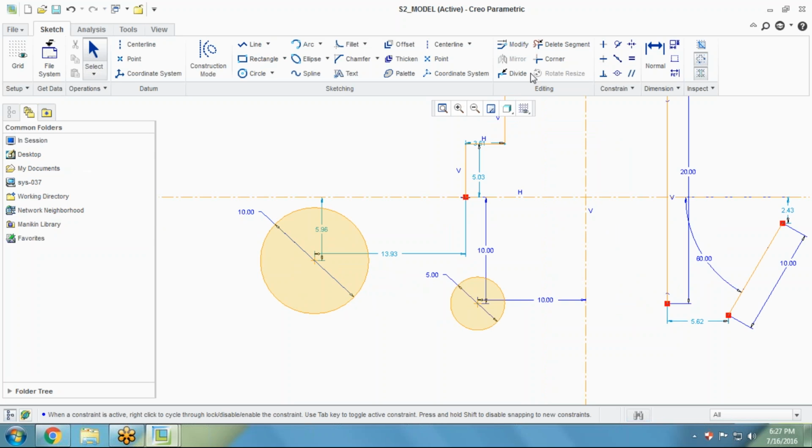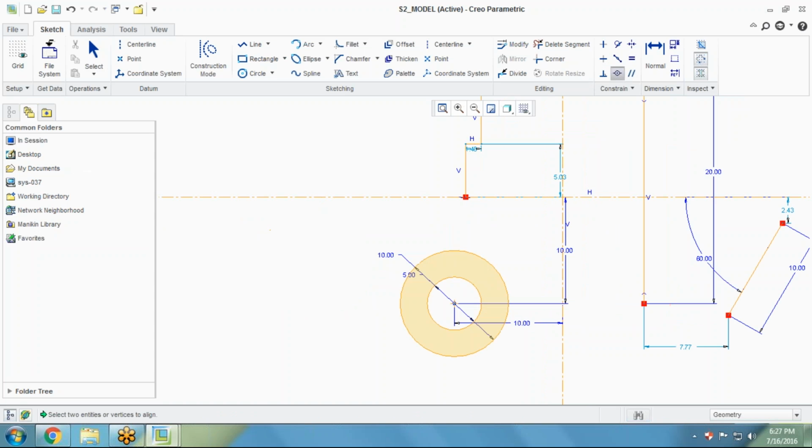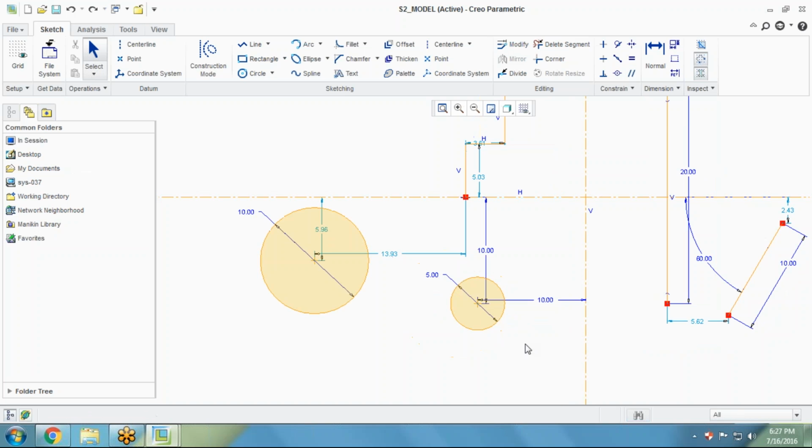So now the next operation I'm showing you is coincident. Just click on this point, click on this point. Now I'm asking you one thing: which circle will be moved? The second one, just because the first one is basically the strong one. So this is the weak dimension, so this object will be transformed accordingly.